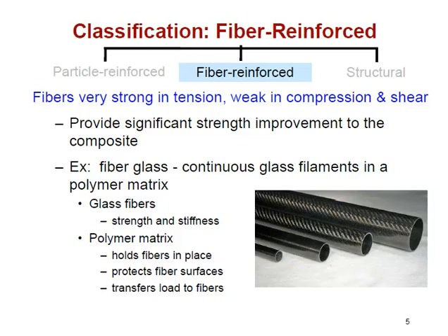It's holding those fibers aligned with their strong tensile axis towards the tensile stress state that the part will be subjected to. And of course, the secondary main reason the matrix is there is to transfer the load to the fibers, since you can't very effectively grab onto fibers, maybe at a transfer fixture on the end.